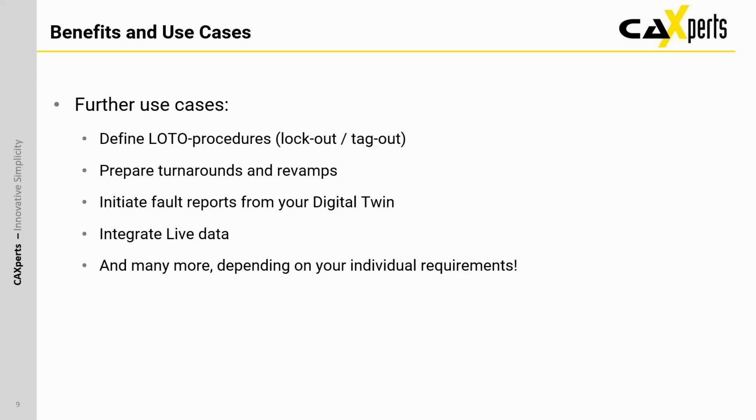And with UPV, you can prepare that by preparing reserved spaces for scaffoldings, for cranes, checking if the motion radius of the crane is sufficient in the place where you plan to use it. You can also create reserved or blocked security zones to ensure security and prevent some risk of accidents.